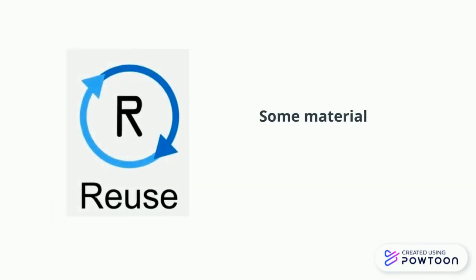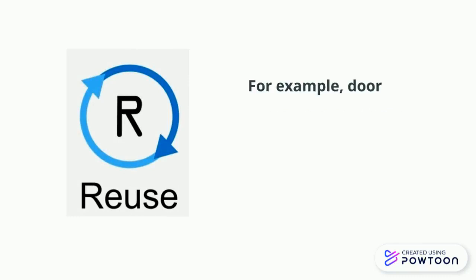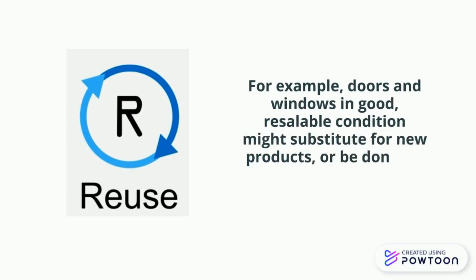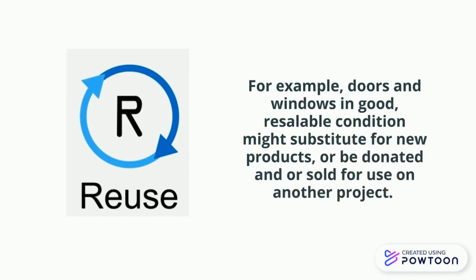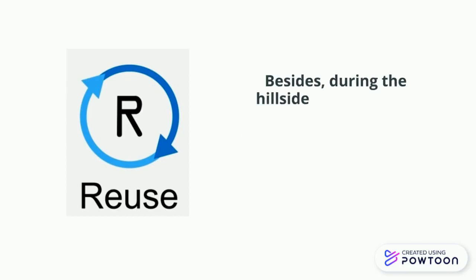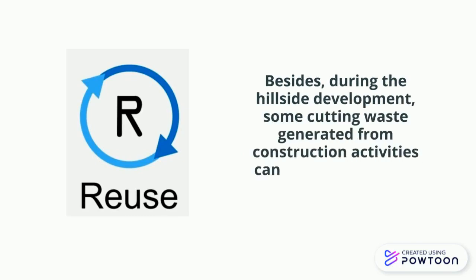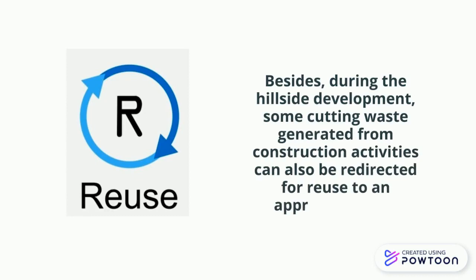Some materials can be reused. For example, doors and windows in good, resaleable condition might substitute for new products, or be donated and/or sold for use on another project. Besides, during the hillside development, some cutting waste generated from construction activities can also be redirected for reuse to an appropriate site.